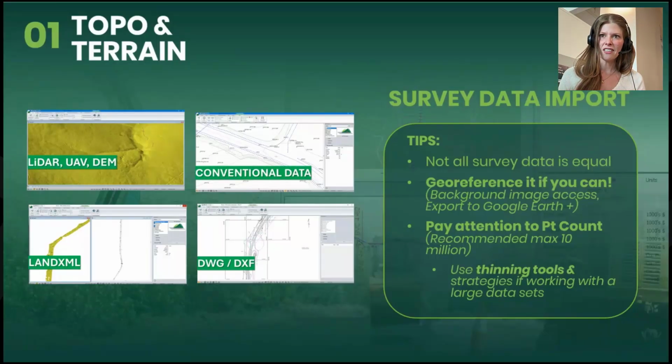So it is an engineering decision for what type of data you are comfortable using and for what stage of design. If you are working with, say, 50-meter data from an SRTM, that data quality is not going to be nearly as good as something that was, say, perhaps collected with LiDAR, where we've got a much, much tighter point spacing. So the data that goes into RoadEng is going to be the basis for all of our earthwork calculations, all of our details that come out of it. So just making sure, step 1, you're comfortable with what you're working with from a survey side.